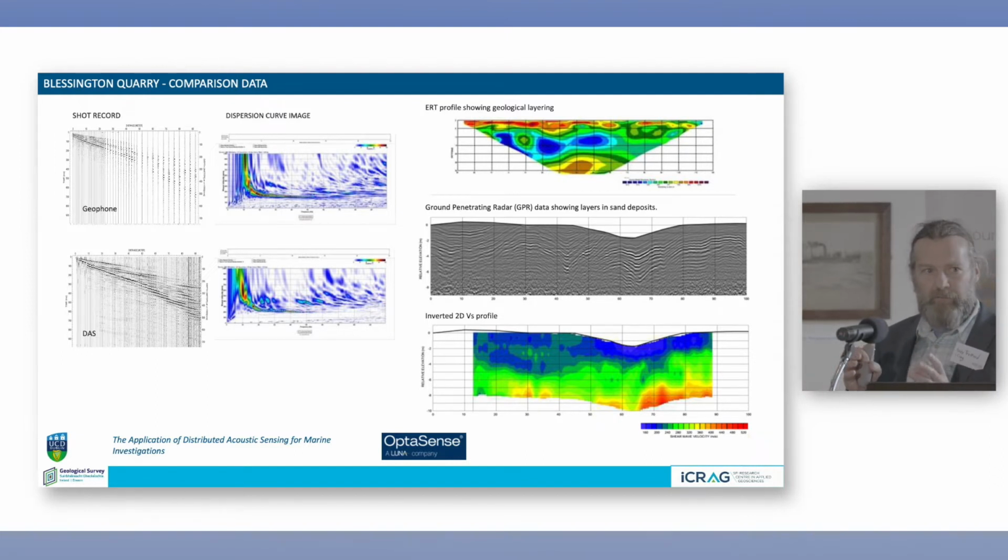One of the main benefits of using acoustic sensing in this way, with fibre optic cables, is that you're not limited by the number of sensors. Typically you'd have hydrophones or geophones at set intervals. With this, we use the whole of the glass fibre core as a sensing element, so we're not really limited practically by the distance we can look. I'll show you later, we've used up to 1 kilometre long cables for the research, but we're not limited to that.